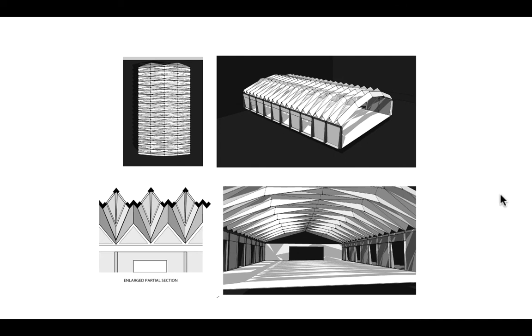Architecturally, there are all kinds of possibilities here. When we start to think about more complicated folds and shapes, we start to realize that we can impart a real architectural grain to a space below. So here again, we've got that idea about a beam arch, right? A beam that's kind of curved so that it puts more of the structure into compression than into tension, kind of gets out of the way of the tensile area. This gives us a taller space in the middle.